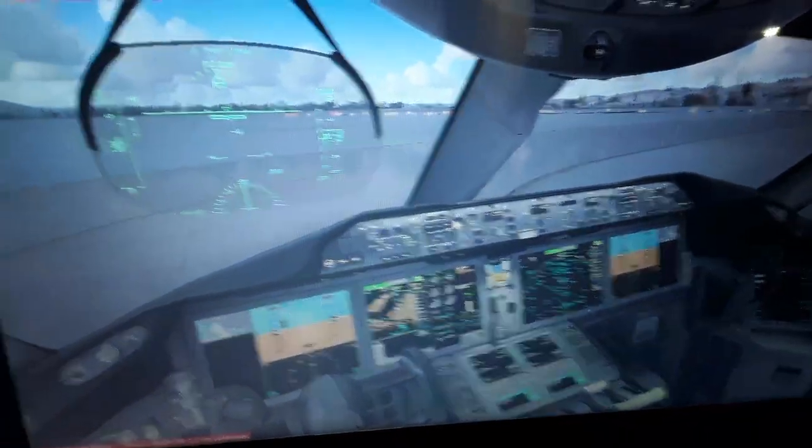We can see also the magnetic north pole and the geographic north pole, the magnetic variation depending on where we are in the world. We have also the GPS position of the aircraft, and also in the terrain map you can see in the horizontal profile the airports around you, where they are located, and the distance from our aircraft. Also around each airport we have the display of the runways and the taxiways, the runway length, the runway heading. Also we have the name of each airport with a 4-letter code name. So we have LSZH in Switzerland displayed in the navigation display.